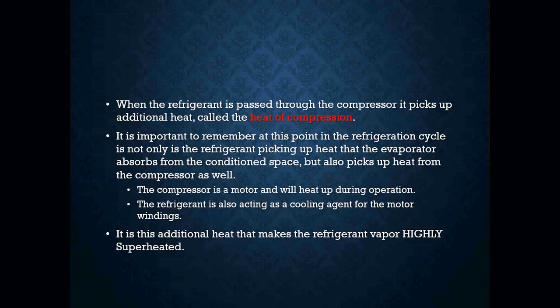It's important to remember that at this point in the refrigeration cycle, the refrigerant is not only carrying the heat that the evaporator has absorbed, all of that sensible and latent heat from the space, but we are also picking up heat from the compressor as well. The compressor is a motor, guys. When it runs, it's going to heat up.